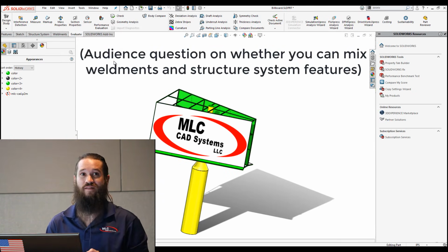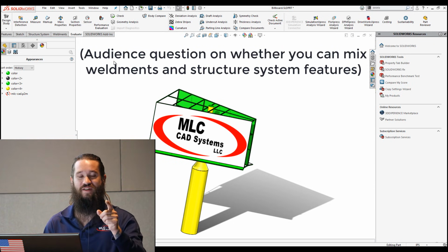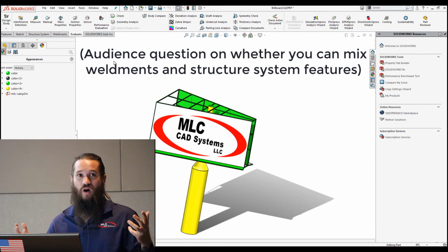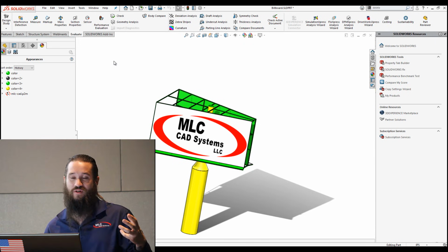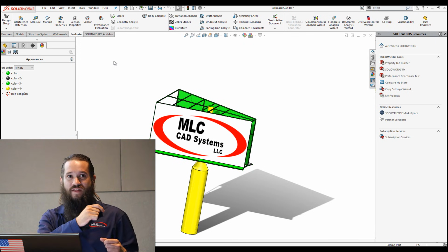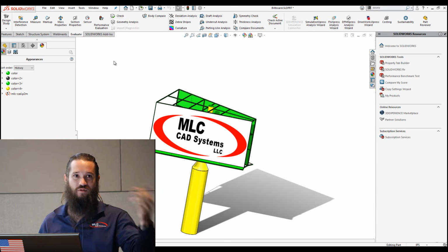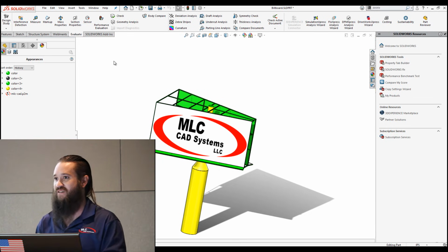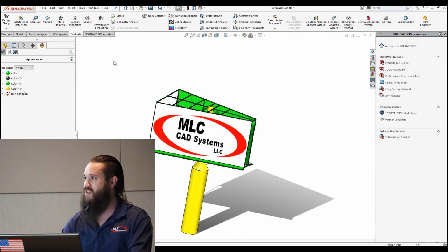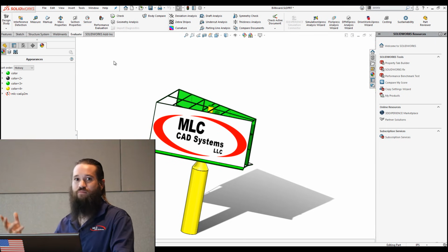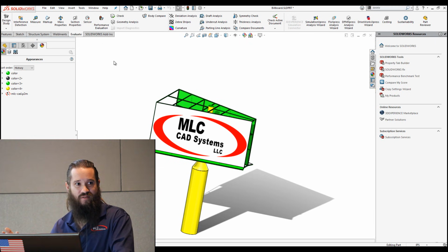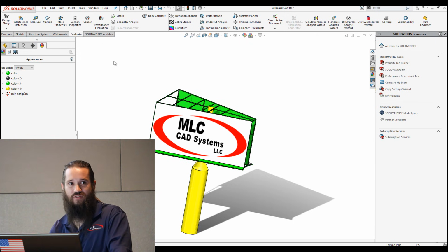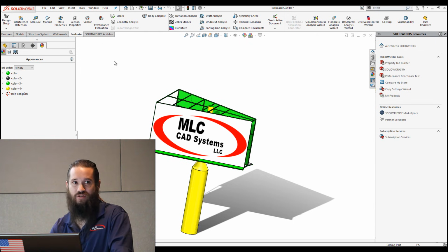No, you cannot. I'm glad you asked that because that was my first thing. I was like, oh, awesome. I can just use structure members to create all my members, and then to do all the trimming and stuff, I'll just switch over to weldments and do end caps or whatever I want, but it doesn't let you mix and match. You would think that you could because they use the exact same profiles for their profile definition. But you can't mix and match features. So end caps don't work, gussets don't work in Structure Systems. That's all normal extrudes for plate.